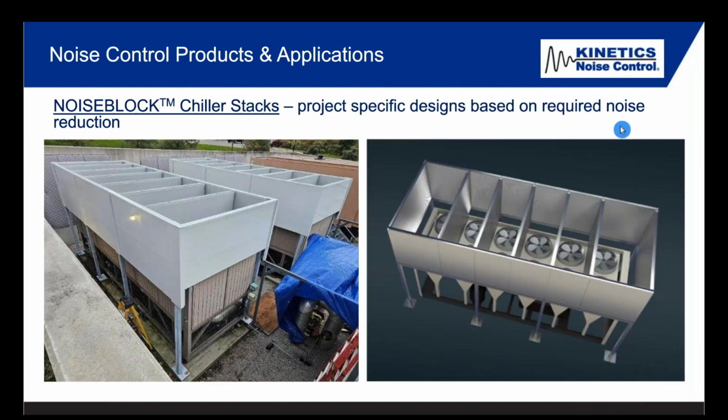We look at air-cooled chillers. Remember, we talked about there's 2 types of noise. There's the upblast fans at the top, and there's the compressors at the bottom. And so we want to look at that. And these are chiller stacks. These are all perforated inner shells, perforated baffles, solid outer shell. Comes with optional doors if somebody wants doors to get in. This shows you an equipment yard here with some curtains, but it actually shows these are all structurally designed and PE stamped in-house to meet the local IBC code, and no weight acts upon the unit.